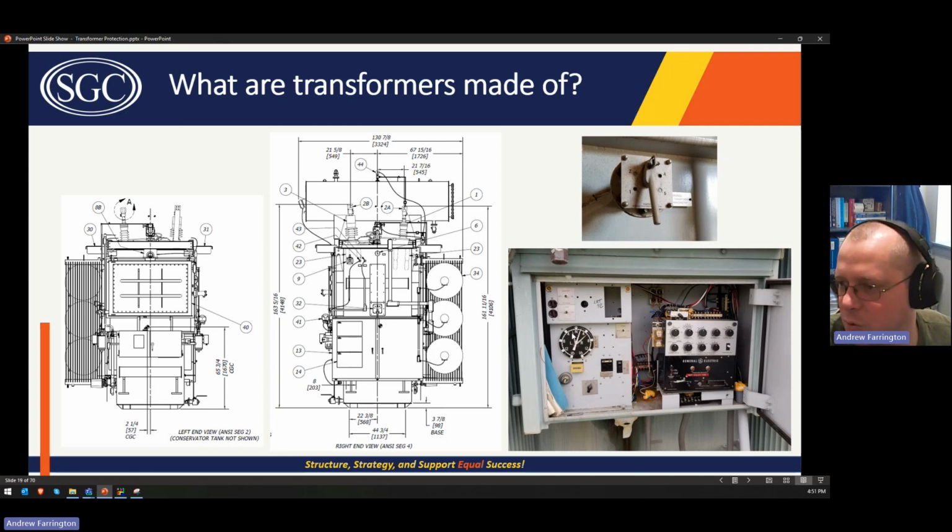So this shows you the minimum tap and the maximum tap that the LTC has moved between since the last time it was reset. So this particular LTC looks like it operated between maybe 1 or 2 lower and about 5 raise, and neutral is within that area. So this seems like they did a pretty good job of setting the de-energized tap changer position such that the LTC operates around neutral. But that's how you'd tell.